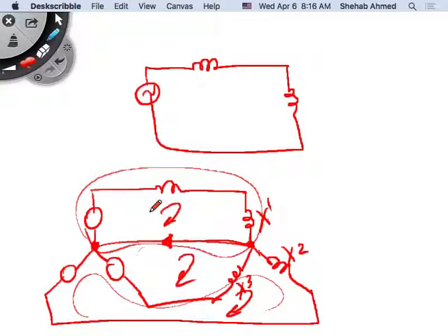But in this approach, of course, what's happening? You have an interconnection. The different phases are going to be affecting each other. Why? Because this current here is due to current contributions from phase A, as well as from phase B, as well as from phase C, right? The neutral current is the sum of all the currents here, so this neutral current is going to be linking all the circuits together.